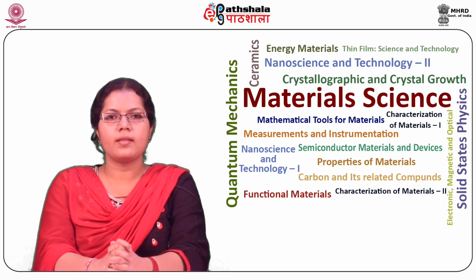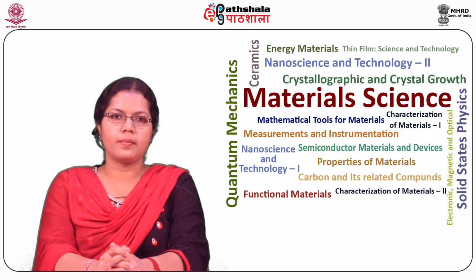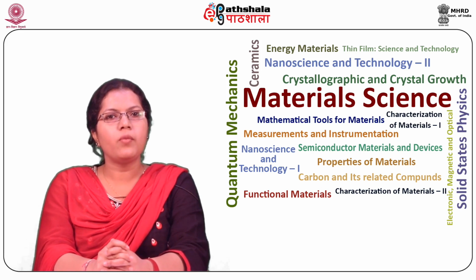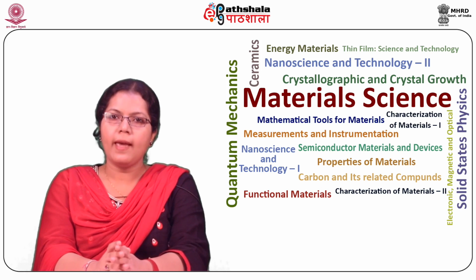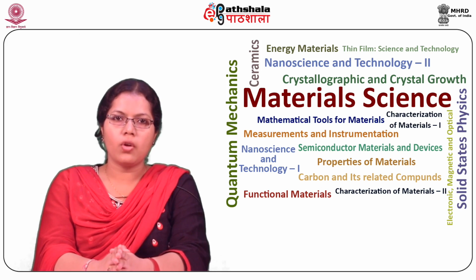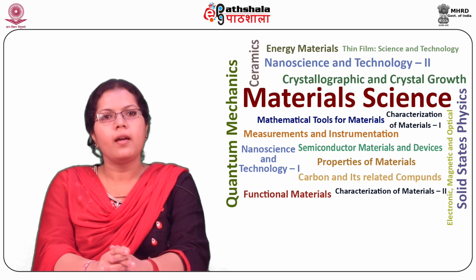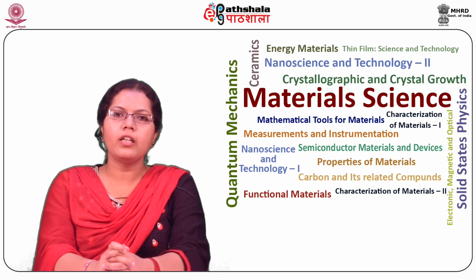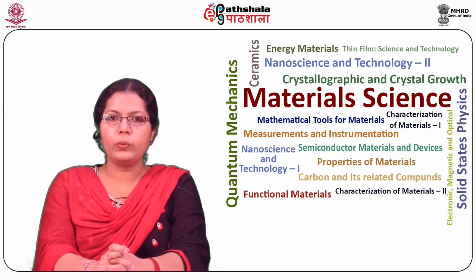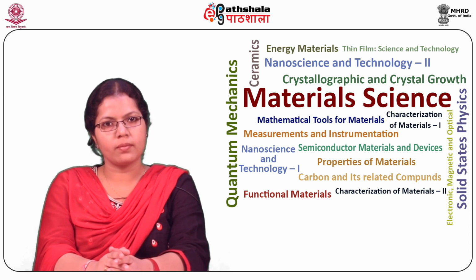This requires that there should be minimal losses. Ferromagnetic materials should never be used as eddy current losses in them are appreciable. The use of inductors having ferromagnetic cores is completely ruled out for high frequency applications.